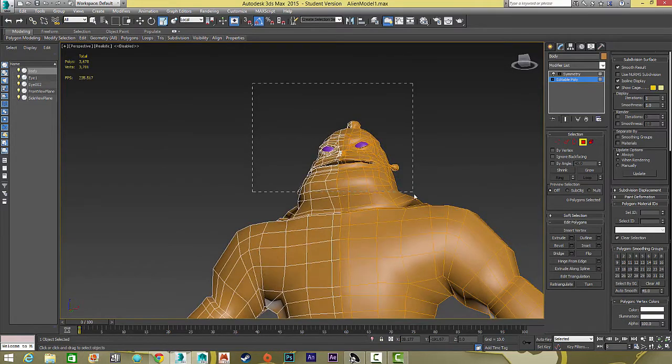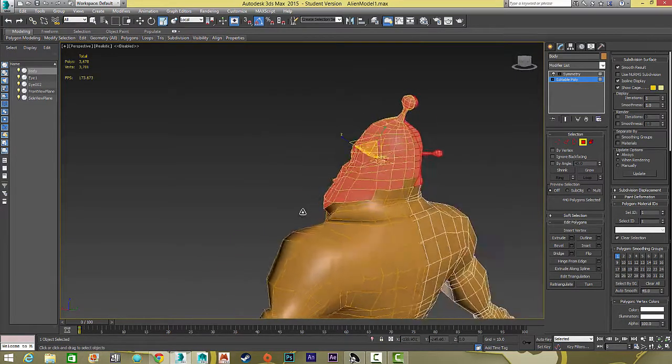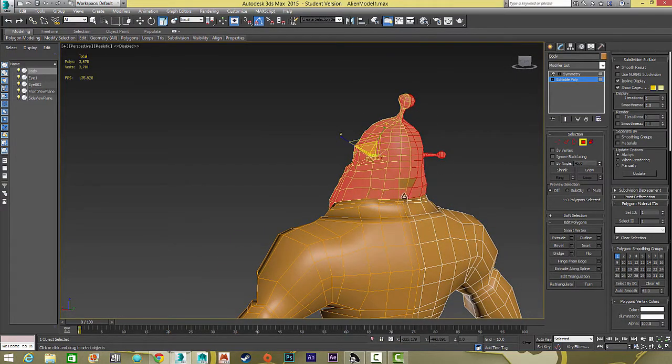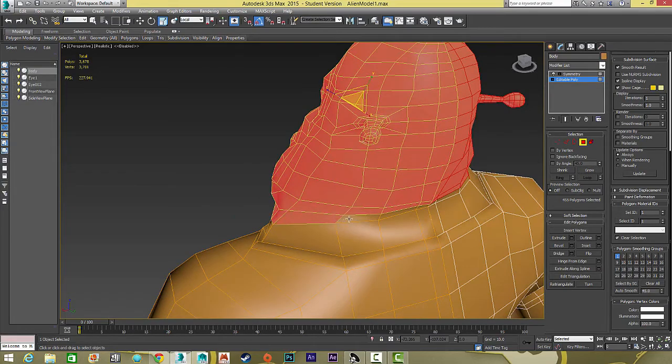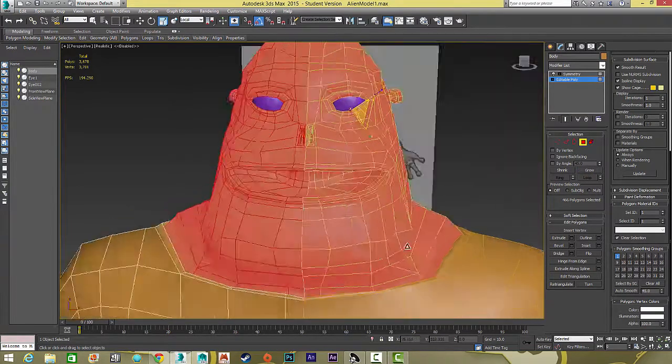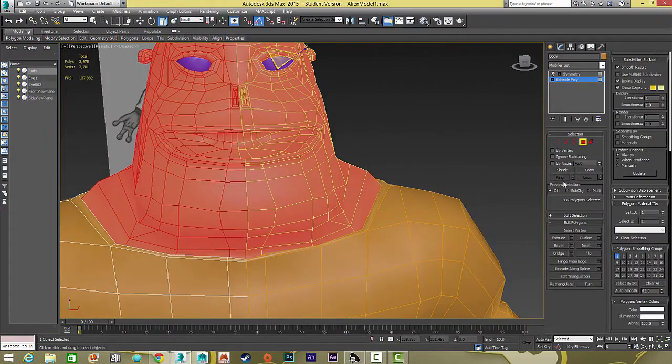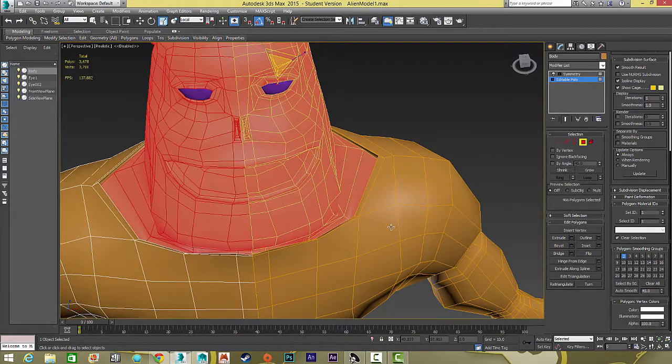So the entire head needs to be one smoothing group compared to the clothing. So let's see if we do grow. Let's make sure we try to get that whole loop. Grow one more time, and exactly one more time as well to get that inside area. That's more than the 34 degree angle as well. Turn on smoother group 1, turn on smoother group 2. Let's do shrink one time, get just the skin. This is back to smoother group 1.